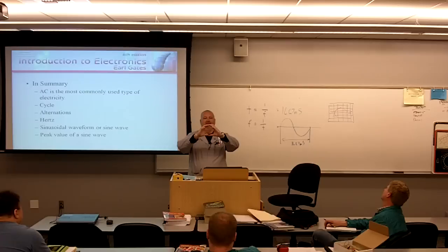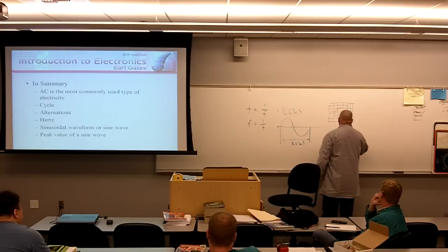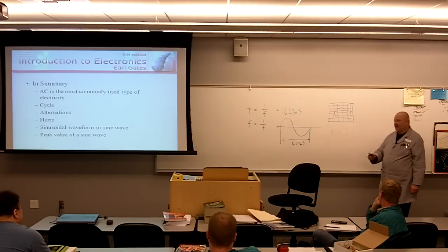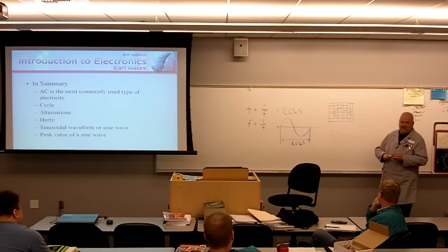I get a circle, because the unknown on my vertical axis matches the known on my horizontal axis, and they mix. If I got something that looked like this, it's a harmonic. If I'm at the perfect frequency, it's going to be a circle. If I'm at double that frequency, it's going to give me one of these things.